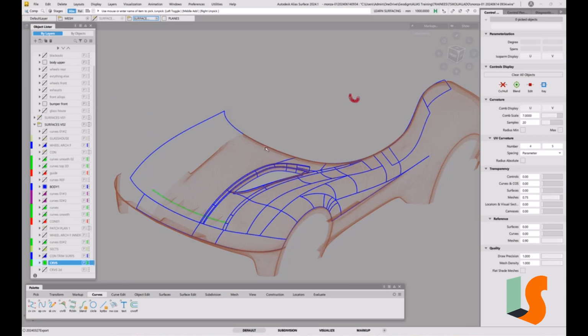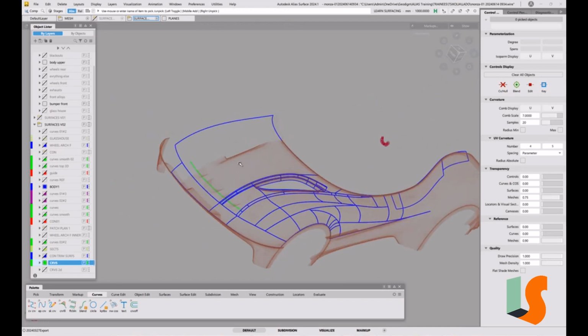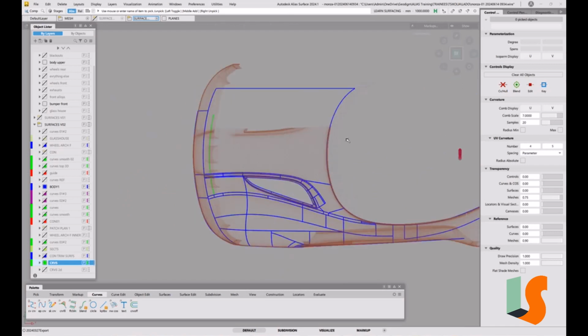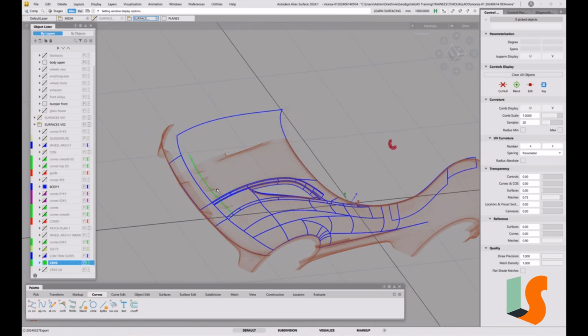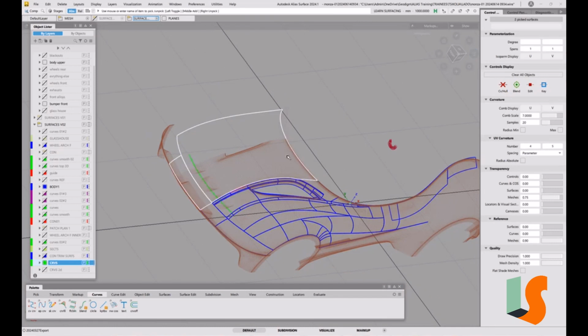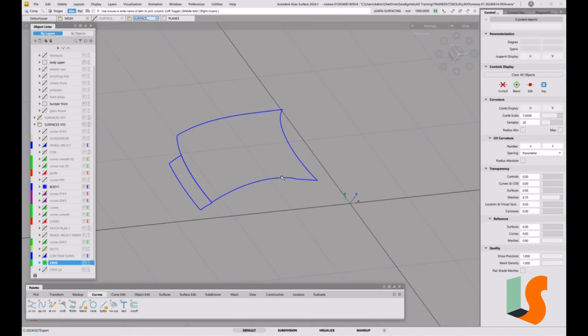That wouldn't make any sense, because then you've got a really difficult job trying to mirror the bits that you want and leaving the bits that you don't want. So it's much better at this stage to split that down the middle. If I go into the plan view, these ones here, I'm going to just trim those to the center. So trim, not trim convert, very important, because then we can get back to the original surfaces if we should ever want to.